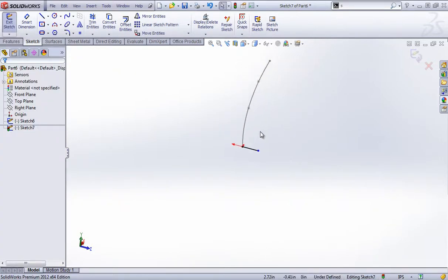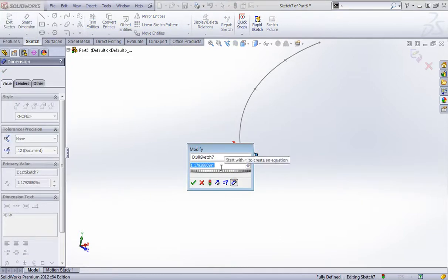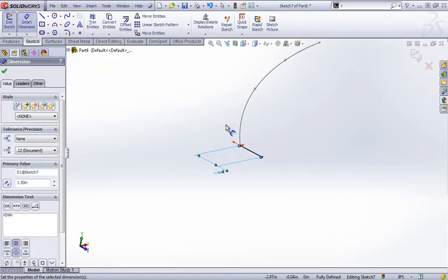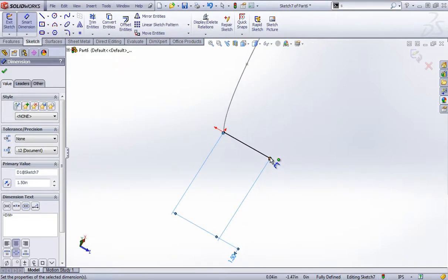And if you wanted a 3-inch diameter circle, for example, for the helix, just like we had for the straight helixes, we can make this 1.5, as this will represent our radius. And this back point is going to represent the outside edge of the curve.